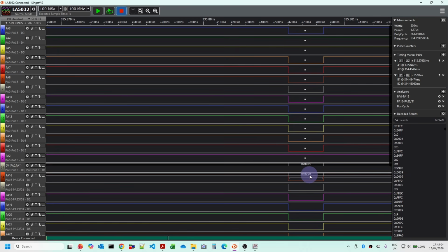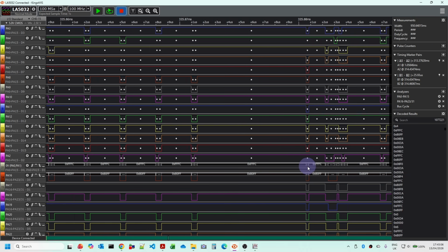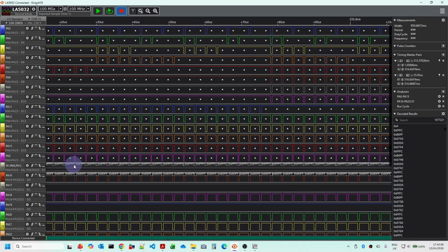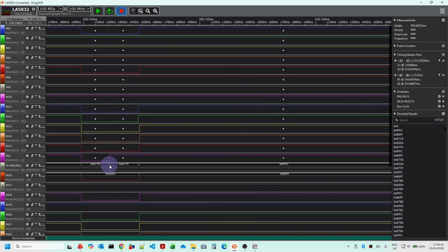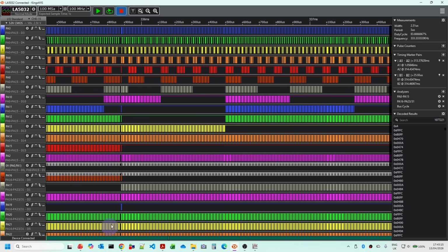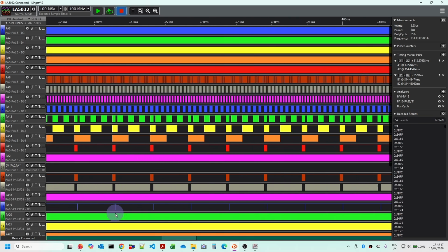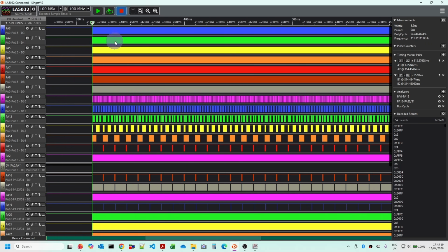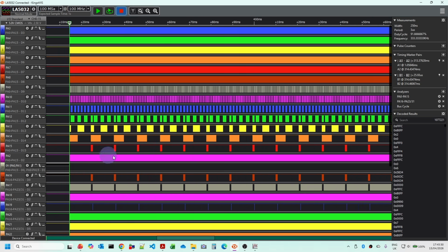In fact, if we look at the next bit here, we've got a general protection fault interrupt occurring again. So what appears to be happening is that it will start counting up for a while, and if we go through all these, you can see that these are counting up through various sequences, but then we're getting another general protection fault again. So we're not getting quite the clean progression going from 0 all the way up to lots of Fs that we'd expect. In fact, we're getting this general protection fault occurring on a regular basis, which is effectively restarting things back at our 9090 based address.